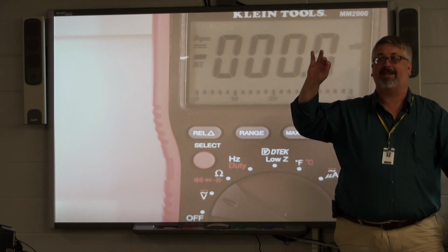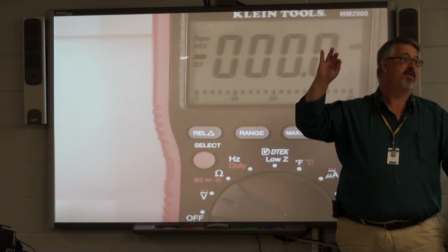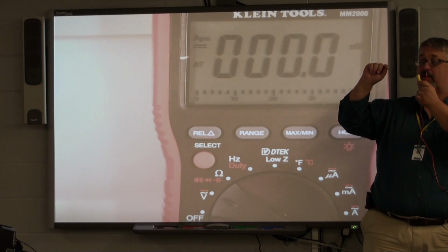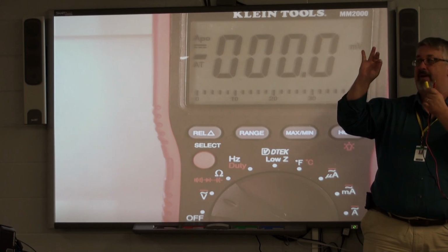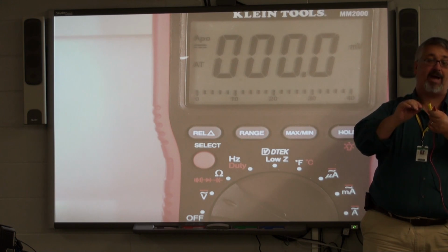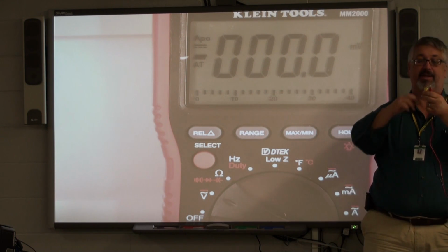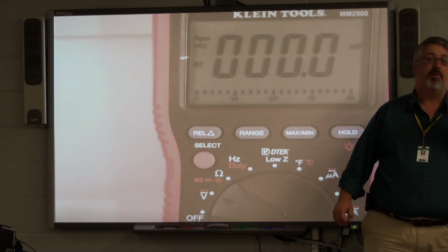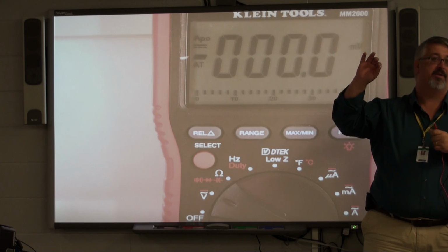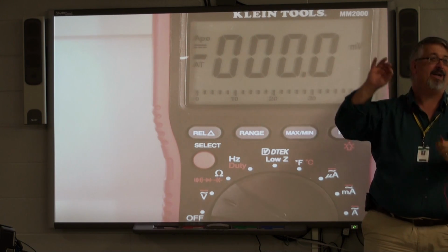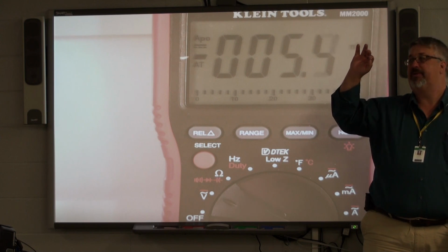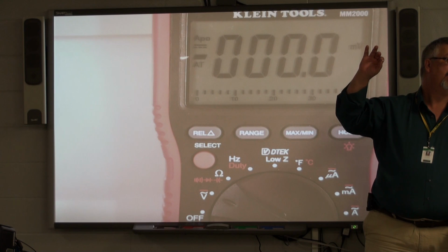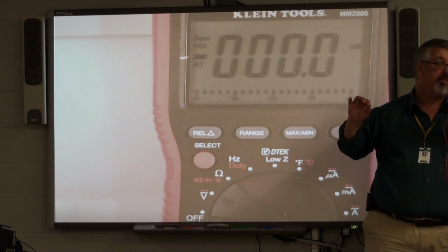Remember when we talked about capacity of a battery? This has a very low capacity. This doesn't have a huge capacity, but it has a lot more current capacity than this little coin battery does. So if I had a flashlight that ran off 6 volts and I put 4 of these together to get 6 volts, I could probably power that flashlight for a few hours before it died. If I stuck 2 of these together and somehow wired that same flashlight to run off these, it'd probably be measured in minutes. Even an LED one would not last hours like it would with a couple of these.